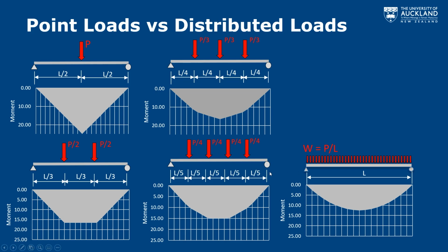And so in terms of a nice iterative design, we will take these 4 point loads, and we will just treat it like it is a uniformly distributed load. So the only point load style analysis that we do would be 1, 2, or 3. And then if we've got 4 or more, we'll just treat it like a UDL. And we'll practice that as we go through looking at different tributary areas and framing in a further video.